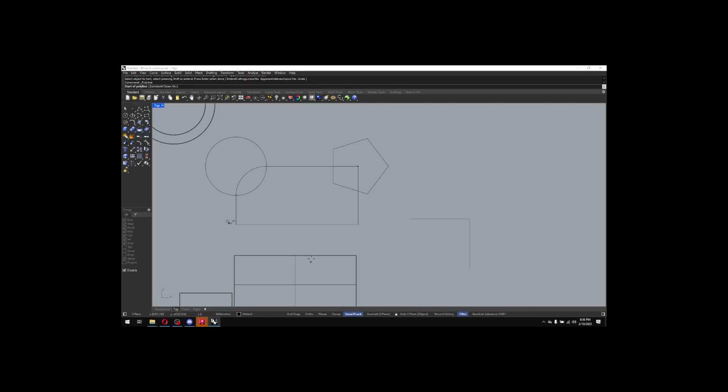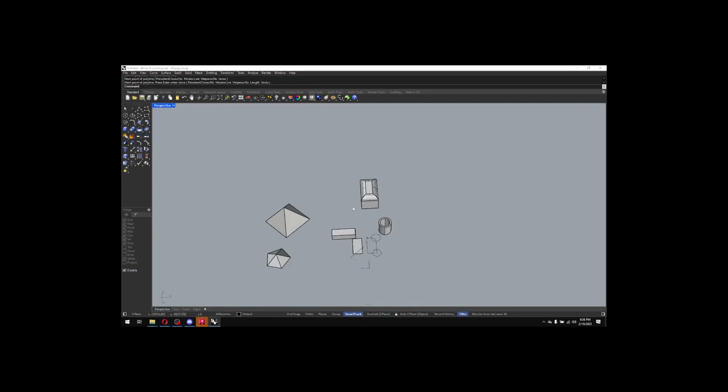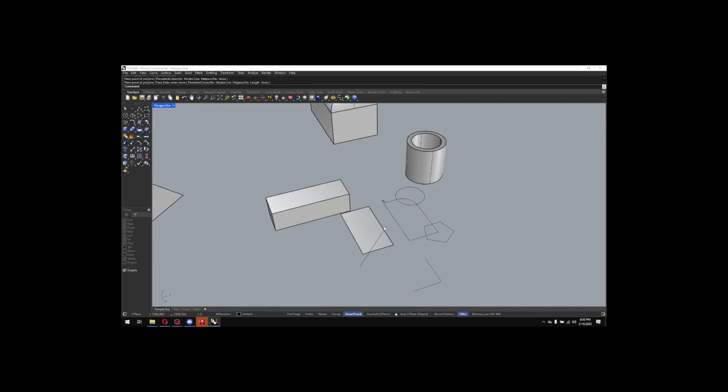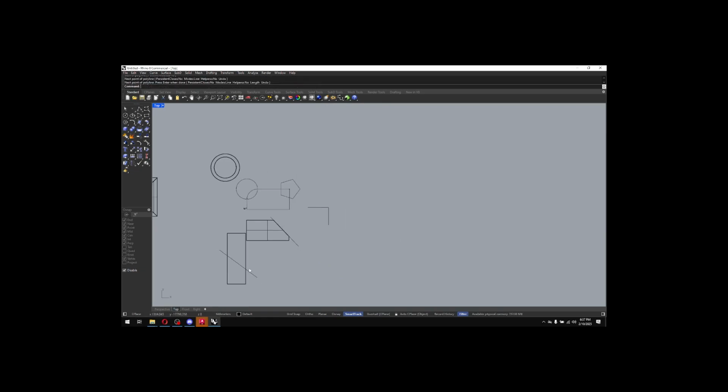Now in 3D, I can also use curves to trim off solid pieces. So I can do trim, select my scissors, hit enter, cut that piece of paper off. It works on big solid pieces as well. So even if it's 3D, I think this one is, yeah.